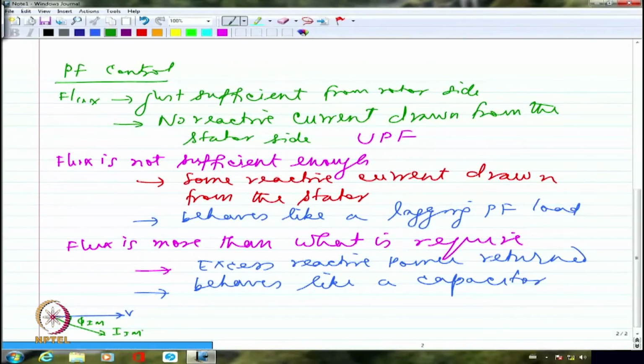Whereas synchronous motor current, I would be able to adjust in such a way that if it is hardly having any mechanical load, I may have only a reactive current. Hardly having any real load, in that case the real power delivered will also be really minimal. So I'm showing the current to be completely reactive. It is at 90 degrees. So it is like a pure capacitor drawing a current.